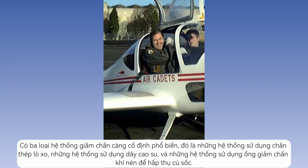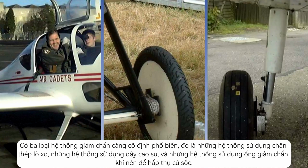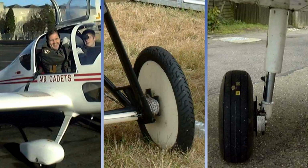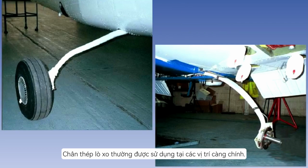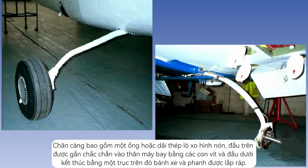There are three types of fixed landing gear shock absorption systems in common use. Those which have a spring steel leg, those which employ rubber cord, and those that have an oleo-pneumatic strut to absorb shocks. Spring steel legs are usually employed at the main landing gear positions. The leg consists of a tube or strip of tapered spring steel, the upper end being attached by bolts to the fuselage, and the lower end terminating in an axle, on which the wheel and brake are assembled.